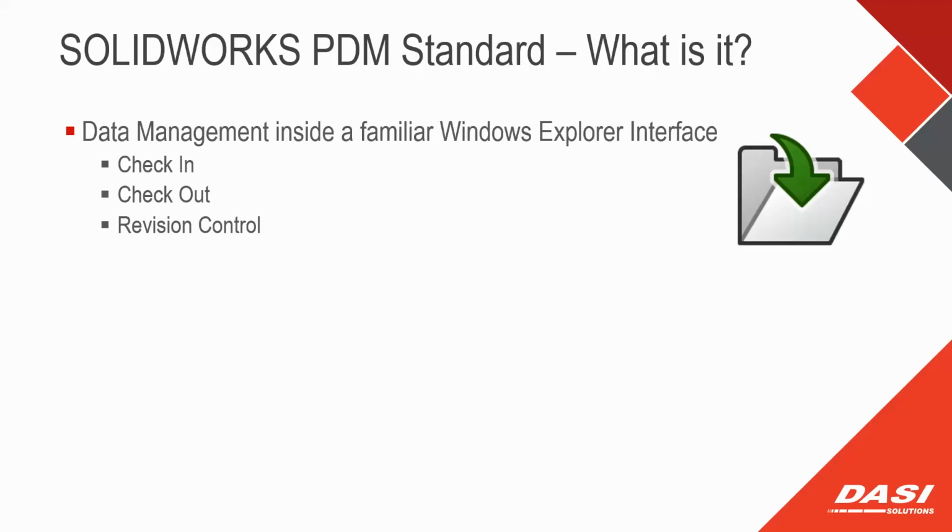What PDM Standard is, it's data management. So when you think about usage, check in, check out, and revision control. When you check out a file, you take ownership, you take write access. When you check it in, you can release write access, which will then allow other people to edit the file. But it is permissions based, so you can control who can do those operations and frankly, who can see particular files at those stages in design, say pre-design to concept to in for approval to actually approved. You want different people to be able to see files at those different states.